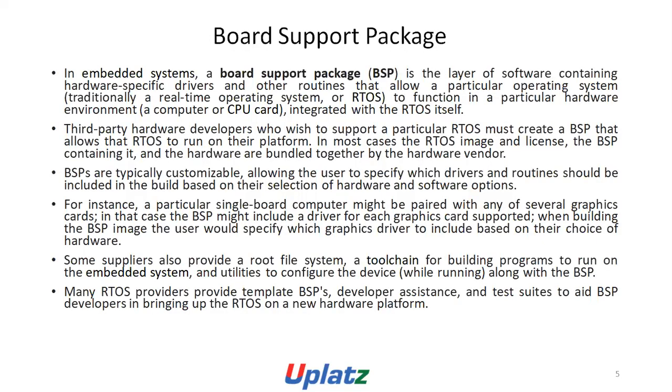Board support package. In embedded systems, a board support package is the layer of software containing hardware-specific drivers and other routines that allow a particular operating system, traditionally a real-time operating system or RTOS, to function in a particular hardware environment.